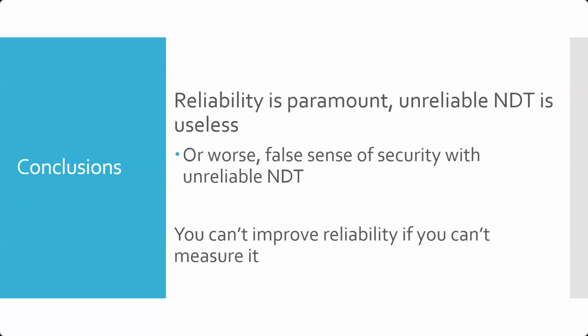But you can't improve this reliability if you can't measure it, and so now you start to have companies like TrueFlaw, who I noted earlier in the presentation, that as part of their services go around and perform POD measurements and provide back a tangible score for how well an inspector is able to perform an inspection. And that wraps up probability of detection reliability.